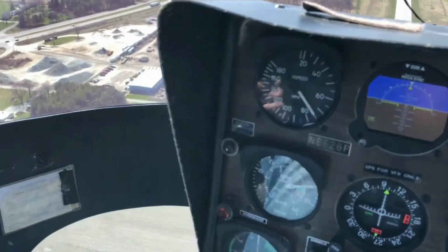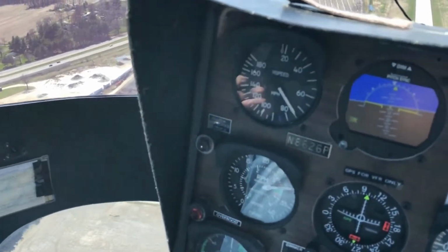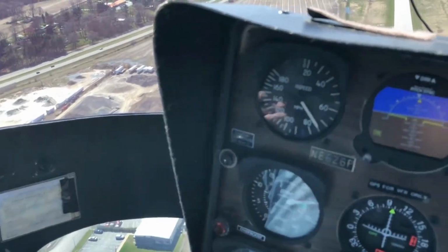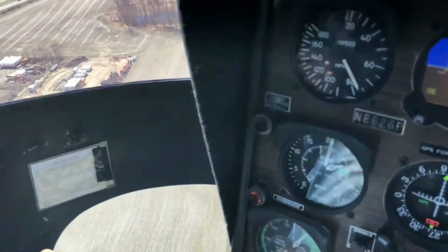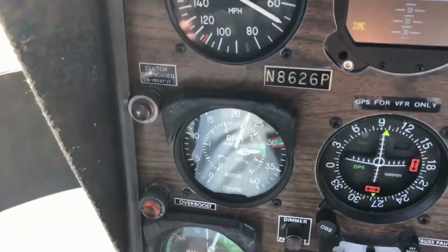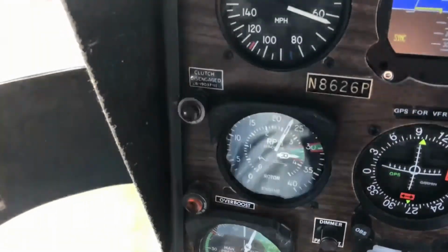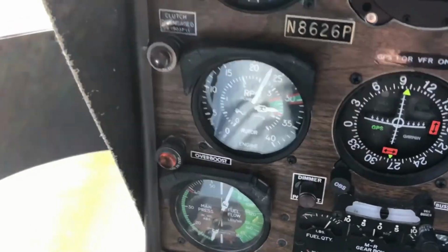All right, we're going to let Gary enter the autorotation when he's ready, and our focal points are going to be airspeed and RPM. 1, 2, 3, all the way down, right pedal. Okay, now that RPM is going to build because we're no longer flying with the engine, we're flying with the upward flow of air that will come up through the rotor system.